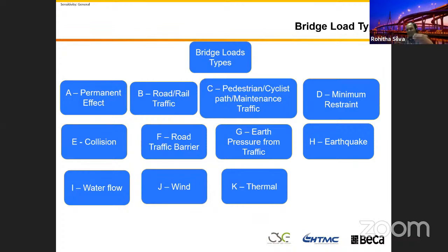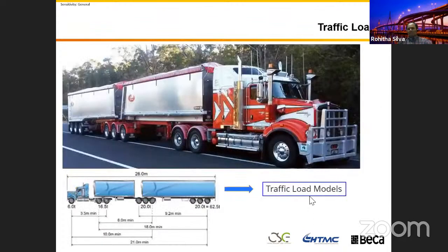In addition, in the next assignment I'm going to give you, one task is to draw an influence line diagram and place the truck on that bridge, to develop, at a couple of sections, the actual force behavior of every section when the truck is moving along the bridge.